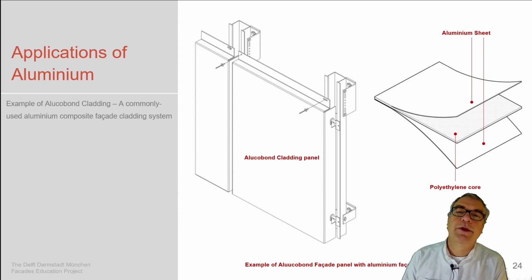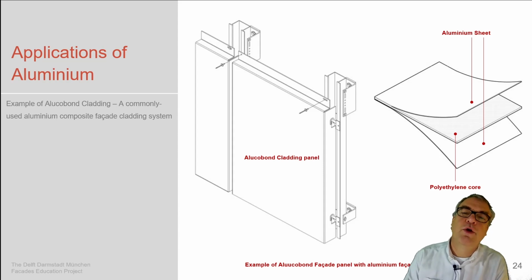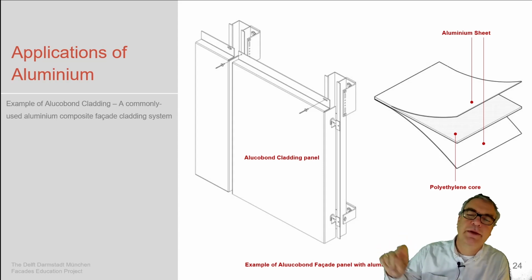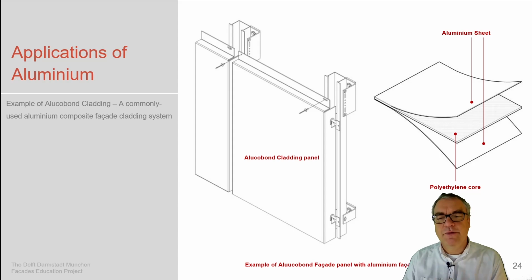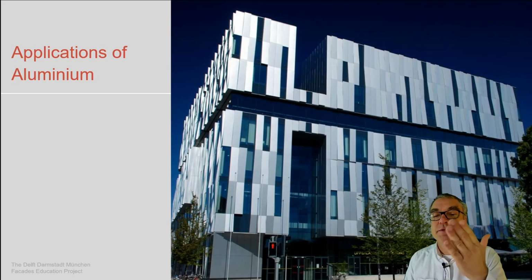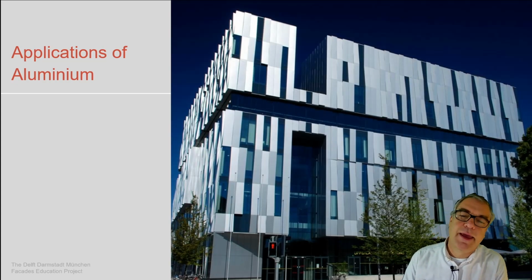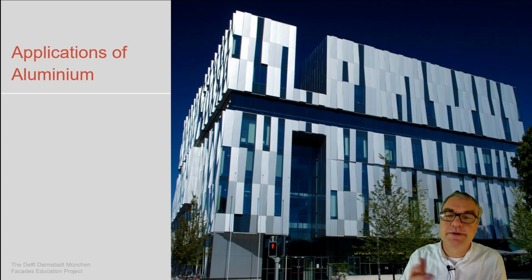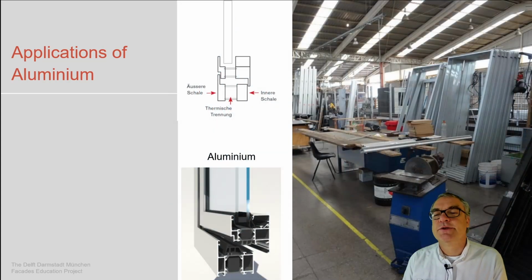These are aluminium sheets, two very thin layers of aluminium sheet with a 5 millimeter polyurethane core, with the consequence that we have a sheet metal with an aluminium surface, a coated or pure aluminium surface, and then still being a sandwich-like structure, being able to go to a certain dimension for its functionality. This is a cladding done in these aluminium polyurethane core sandwich components, as just described.